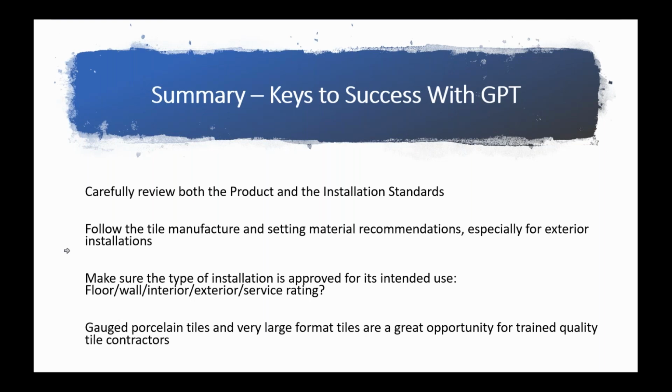And so you can go to their technical manual and get an idea what your favorite setting material manufacturer recommends for this type of tile. And we do the testing too. We do bond tests, we do a variety of things, which is also required in the product standard. Make sure the type of installation is approved for its intended use, whether it's interior, exterior, wall, floor, and the proper service rating.